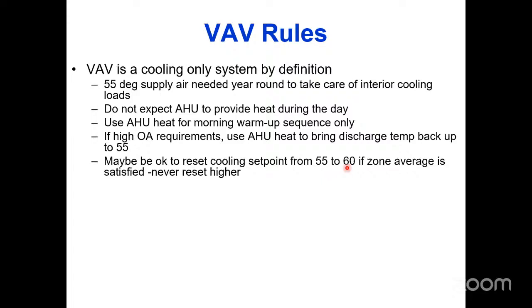However, in the wintertime, I can reset the cooling set point upward because I don't really need to hit the dew point because I don't really need to dehumidify in most spaces. I just need to cool the interior. So 60-degree air is enough to cool the building, but not dehumidify it, and that is okay in the winter. So you can do that.